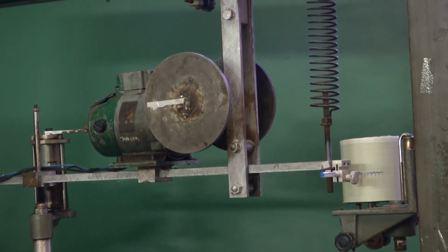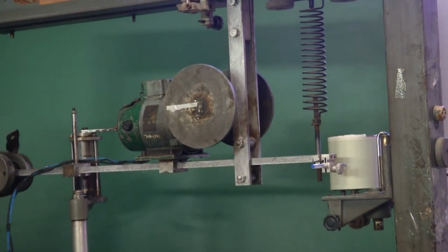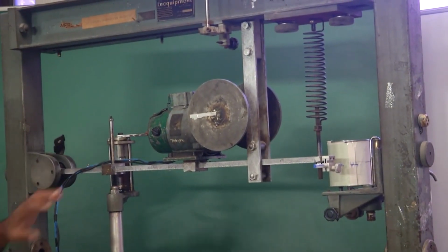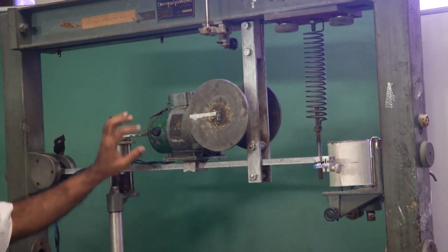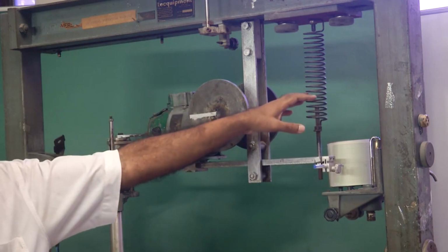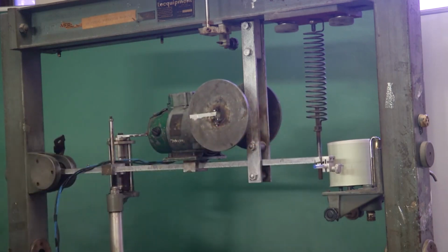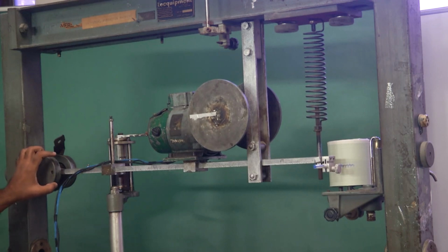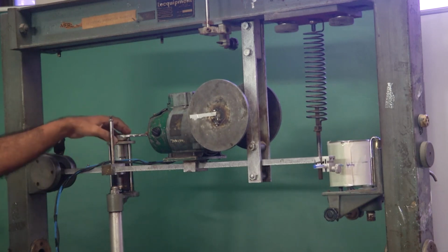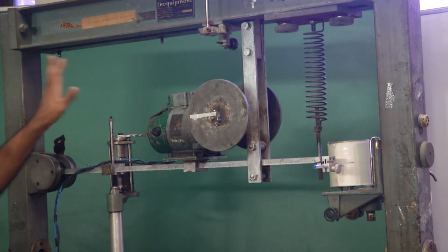Now, the question here is, in this practical system, where is the contribution of damping? Because we discussed that there is a beam which has a motor mounted, that is the mass. There is a spring over here which is another element, and the beam is hinged here. There is no dissipating mechanism that we see. There is no formal dashpot, which of course is there, but we have not at the moment connected it to the vibratory system.